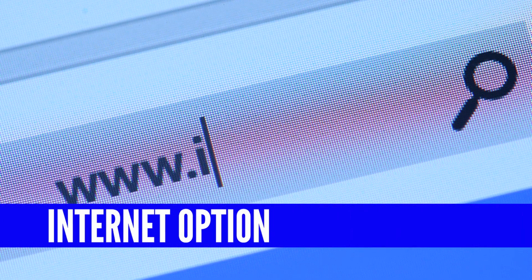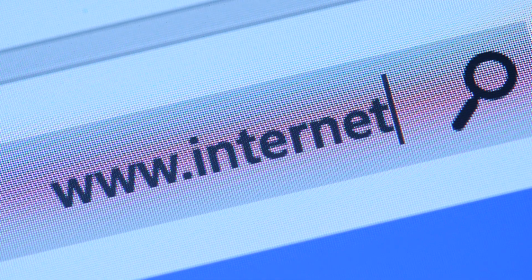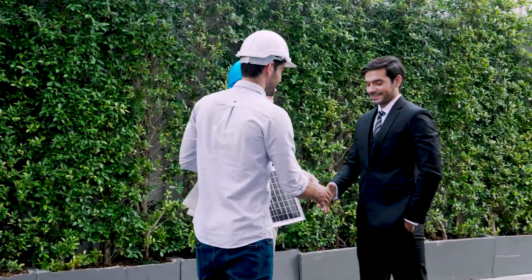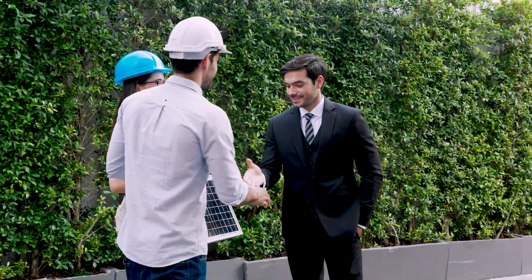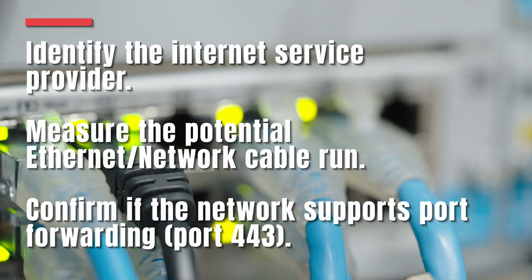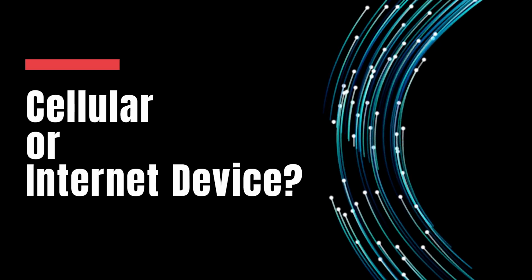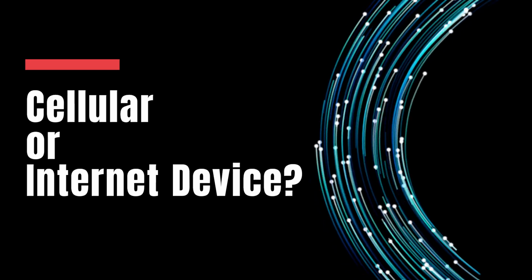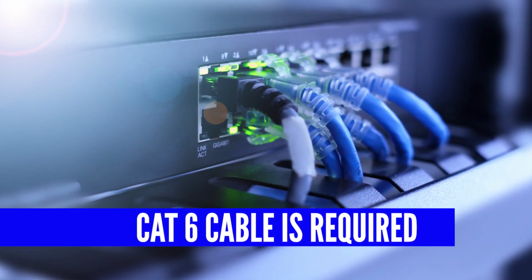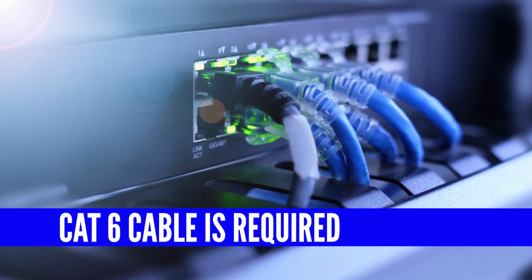Internet option, if applicable. If considering an internet-based installation, in collaboration with the property manager and their IT team, identify the internet service provider. Measure the potential Ethernet network cable run. Confirm if the network supports port forwarding. Determine whether a cellular or internet device is preferable for this location. Remember, Cat6 cable is required, and you'll need a PoE injector if using power over Ethernet.